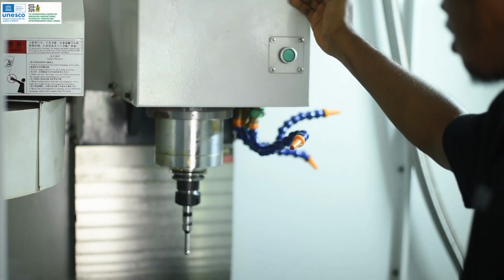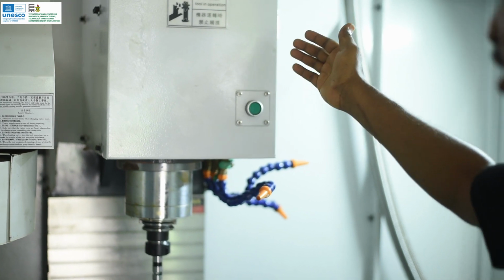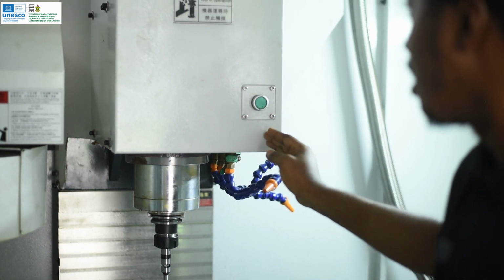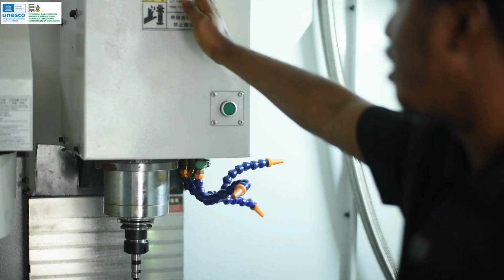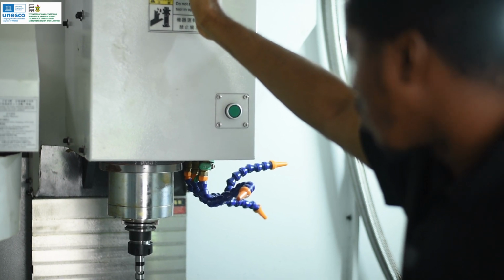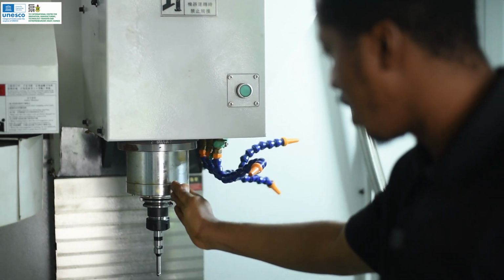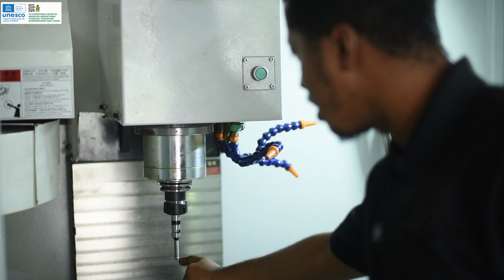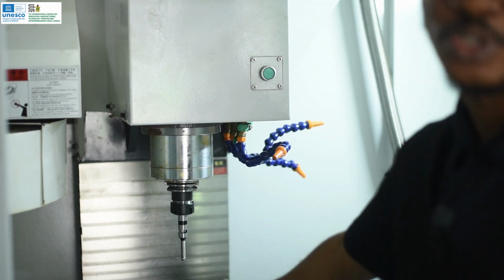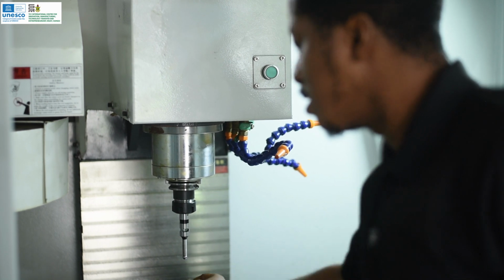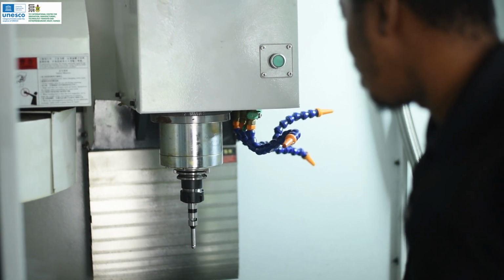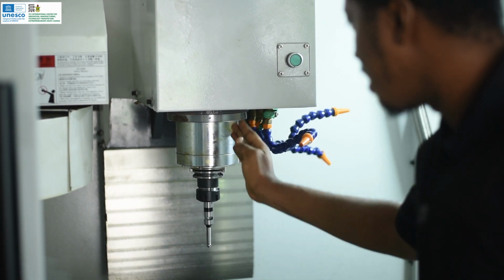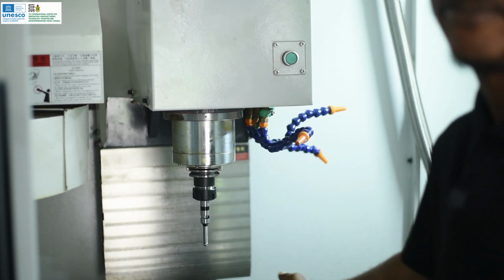So let's explain why we had to use 5 and -5 while finding the edge of our part. Now, when you take your spindle and imagine a line running right through the center of the spindle, through the edge finder, that line would divide this sphere into exactly 2. So if the sphere is 10 millimeters, then the distance between the edge that is touching your workpiece and the axis of the spindle would be 5 millimeters.